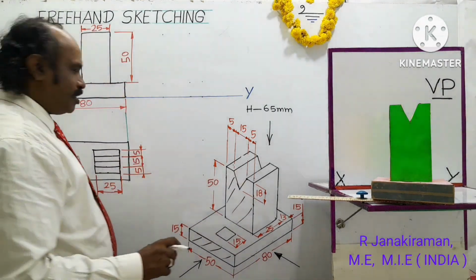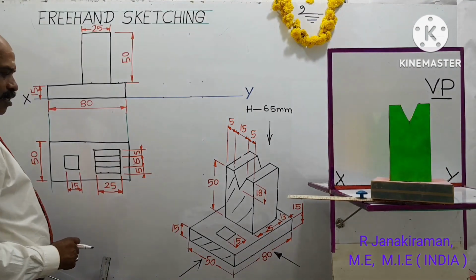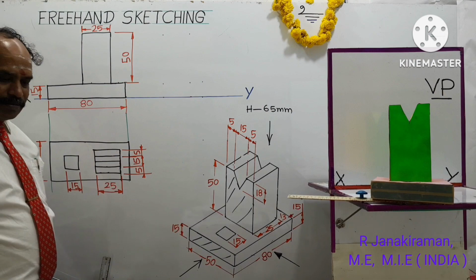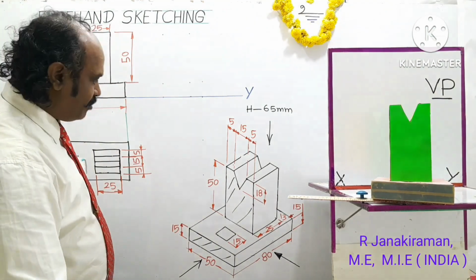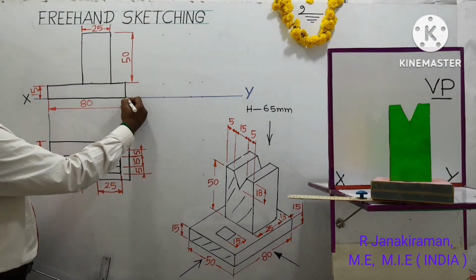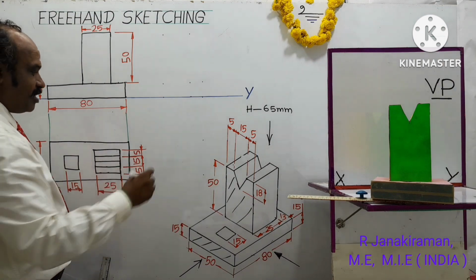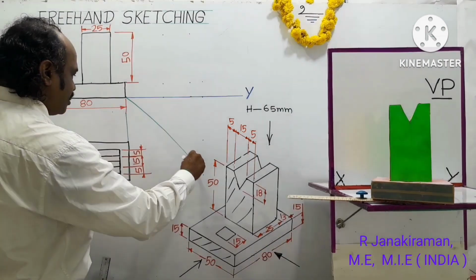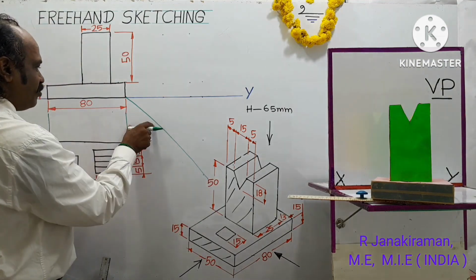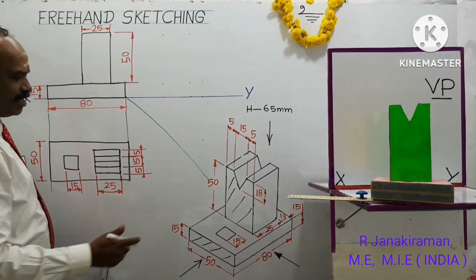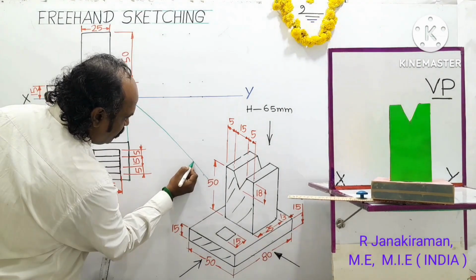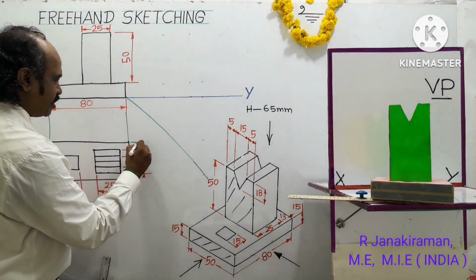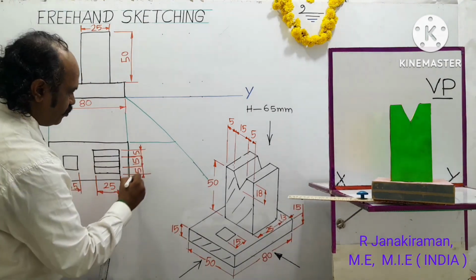These are the portions. The left side view shall be drawn on the right side of the front view, following the first angle projection principle as per the syllabus of BTech students. Take this corner of the front view as reference. Draw one miter line inclined at 45 degrees like this, roughly by hand. At the center you draw one inclined line like this, called the miter line, used to project the side view of the object. Draw a horizontal projector from the previous top view.